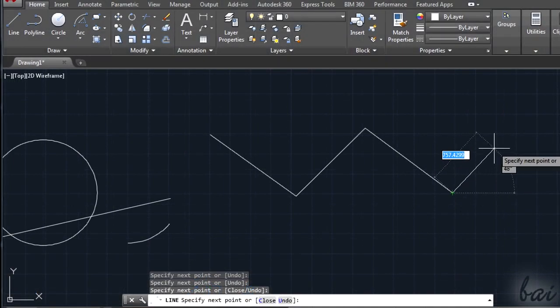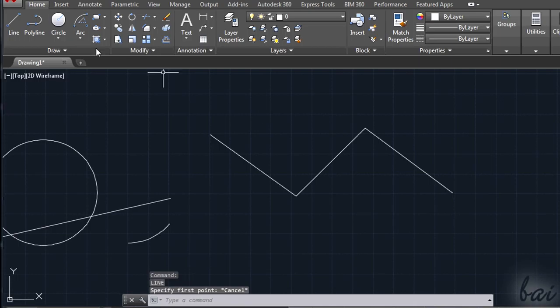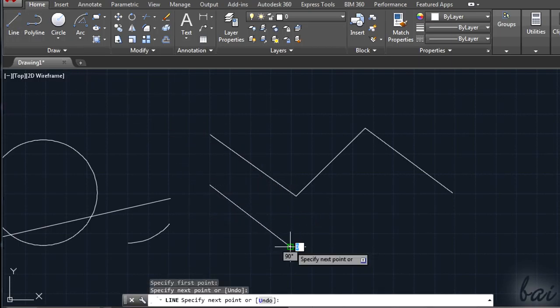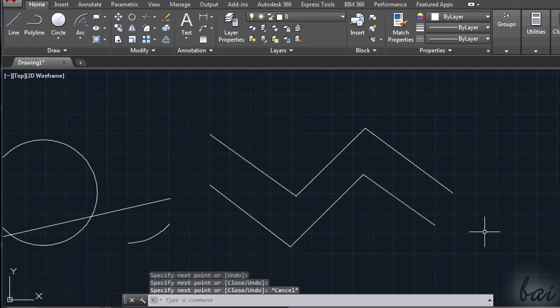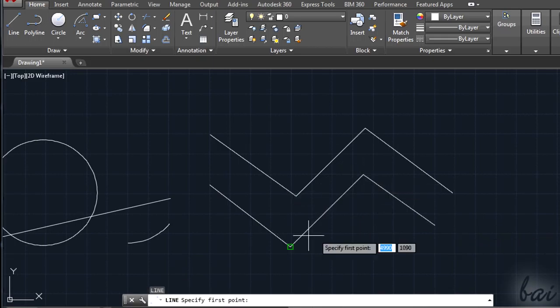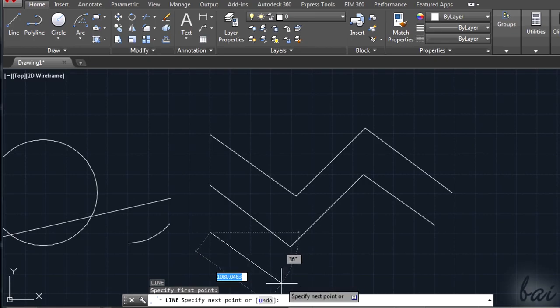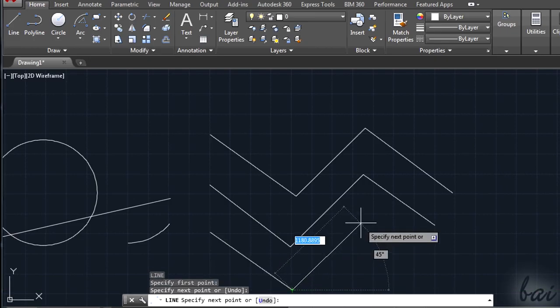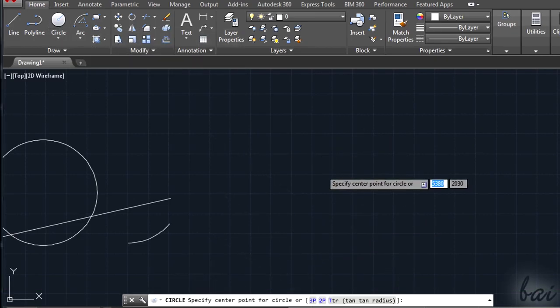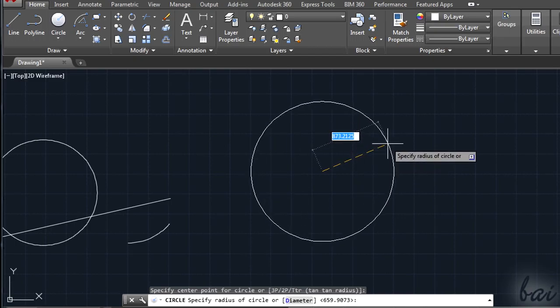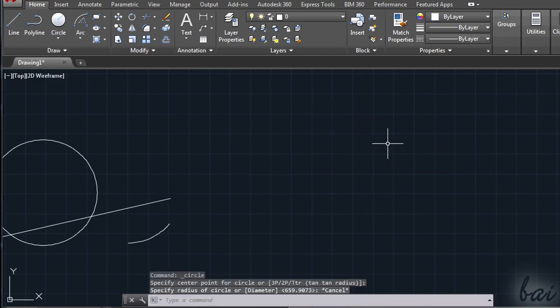Once you finish drawing an object, you may need to click again on its button to draw another one. However, it is enough to press Enter on your keyboard to enable the tool again. Then, while you draw, you can simply press the Escape key to undo the drawing process.